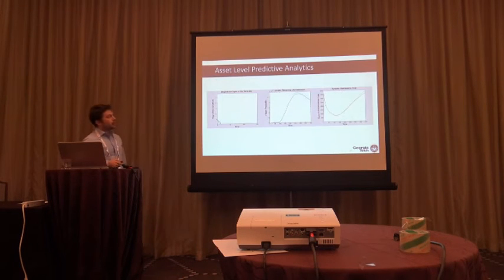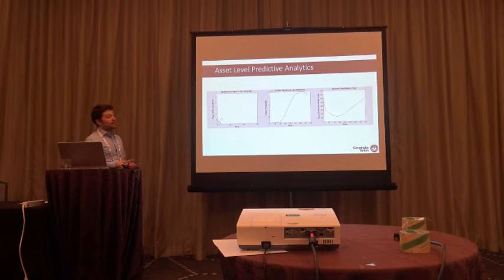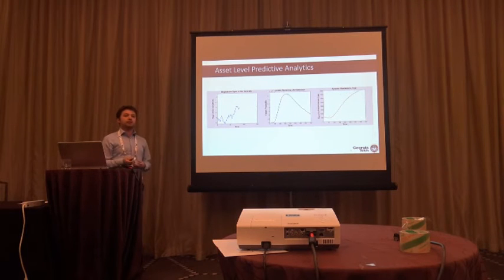So here you can see a quick example of what's happening. You can see as the component degrades, the degradation amplitude for that component starts to go up, so it can detect some sort of a degradation that's happening, so that our remaining life distribution estimate starts to get closer and closer to zero. And adaptively, the dynamic maintenance cost, which shows the expected maintenance cost versus time, the minimum of it starts to get closer and closer to zero. What it says is that I use the sensor information to understand it's getting close to the failure time, and I can detect that, and I can use that information in real time to evaluate the expected maintenance cost at each time period in the future.